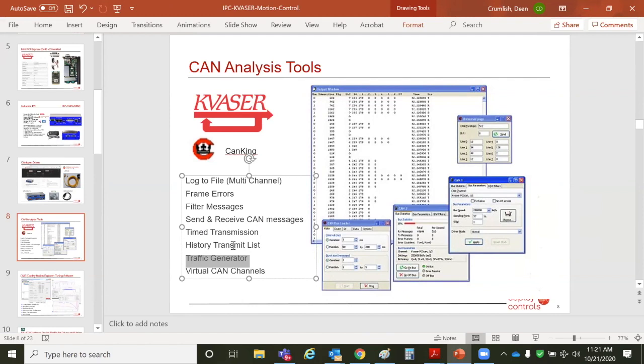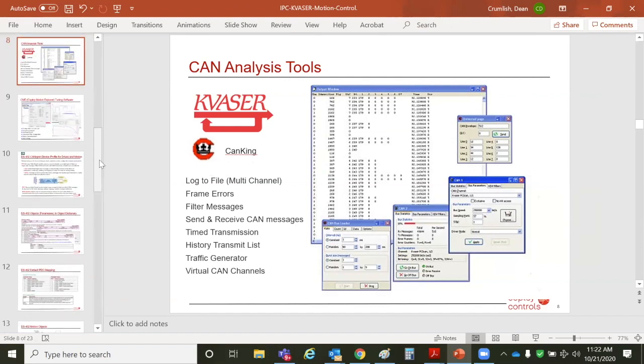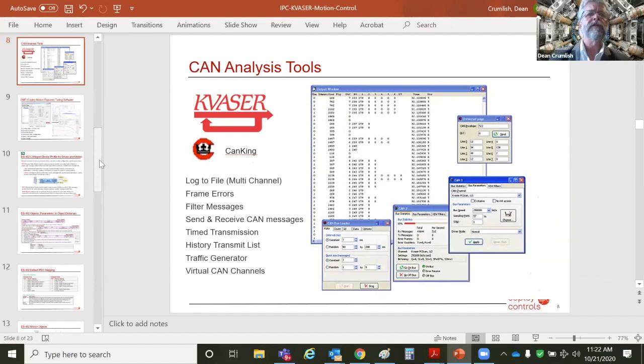The traffic generator is there as a general test. If I want to make sure my hardware's just working without any other software, I can do a loopback between the 2 channels and shoot data for a while to see, as I heat the equipment up, whether it's still working. The other use is in my normal system: since I can specify the range of IDs, I can try stressing my system by increasing the bandwidth used on the bus with a range of messages beyond what are used by the system, and see how the nodes react to messages that they're not expecting. Ah, good tool for testing things out. I like it. Thanks, Troy.